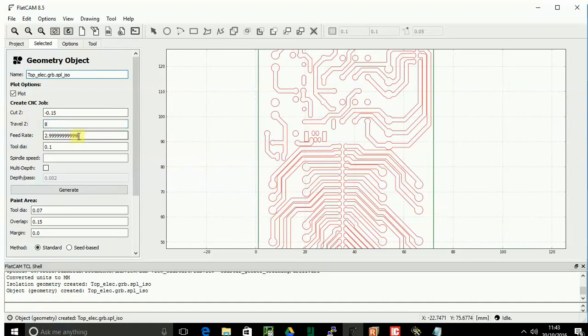And then for the speed of the movement of the tools on the XY plane, it's going to be like 200 millimeters per minute, and this is not to change. This is the same tool diameter. I don't think this is going to have any effect, but I know the speed of my spindle, so I'll put it there.